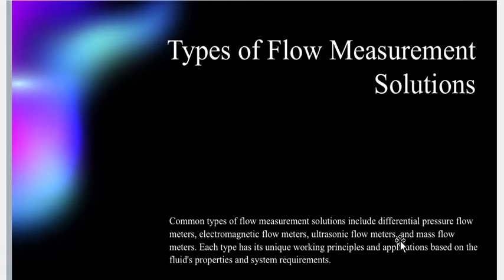These meters use ultrasonic sound waves. To calculate the flow rate, they measure the time difference or the frequency shift of the ultrasonic signal traveling with and against the fluid flow. Imagine with me we have a pipe, and that pipe has ultrasonic transducers on the top and bottom of the pipe.